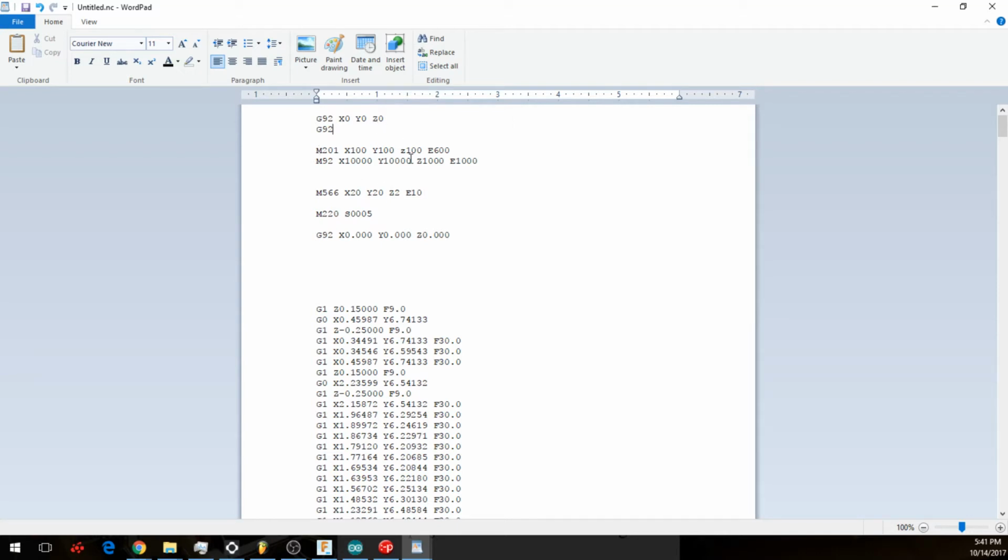We're going to do an M201, which is going to set the max acceleration. And these are values that I have found work pretty good with the specific machine that I built. And then E is setting the extruder value, because this Marlin is meant to run 3D printers, so they have extruders. When you enter this command, it's going to look for you to declare all the values, including the extruder. So we're just going to declare dummy extruder values, even though we're not using an extruder, just to make the code happy.